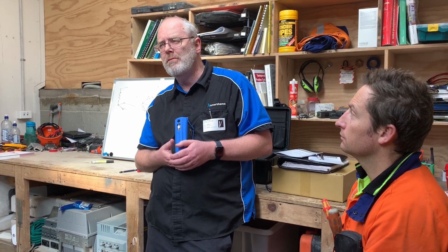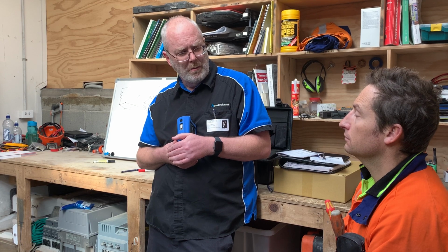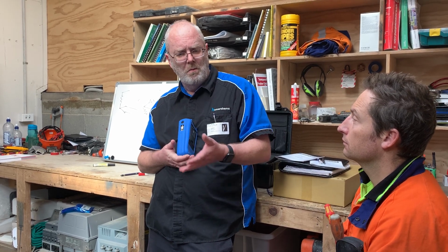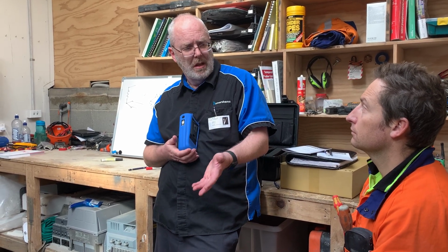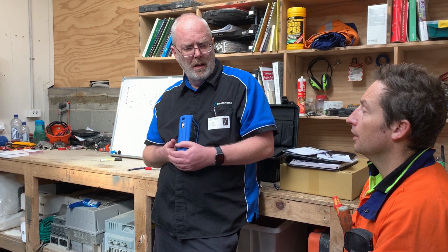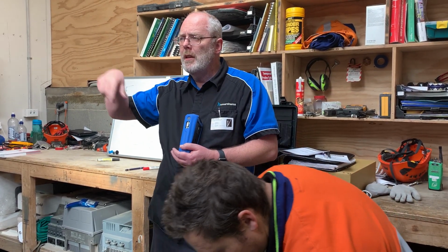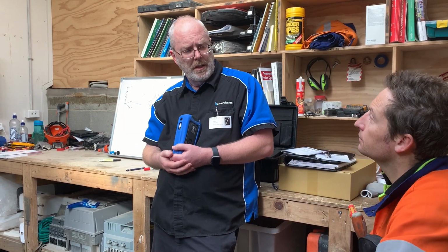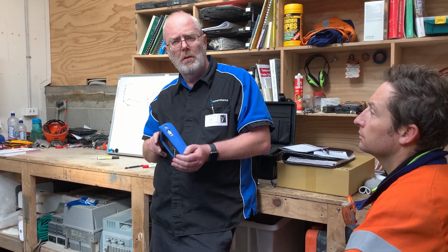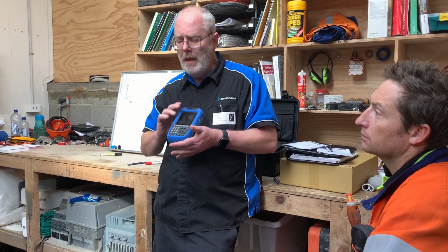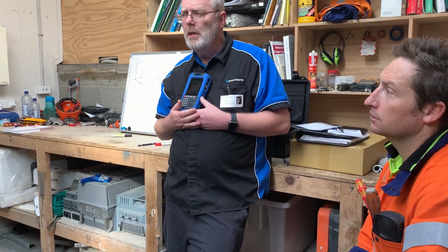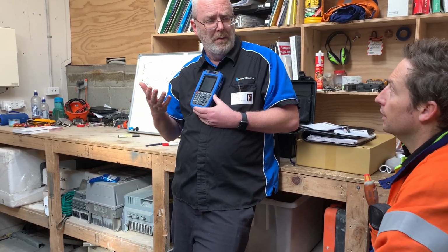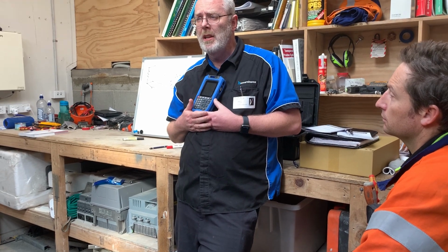Right. It should be pretty simple, I guess, once you know what the transmitter is supposed to be doing. 10 litres is 4 milliamps, 100 litres is 20. It's fairly easy to do that, 16 minus 4 over the total. Yeah. Good question. Anything else you want to know? This isn't a one-time deal. If you have questions, I'm quite happy to take your call.